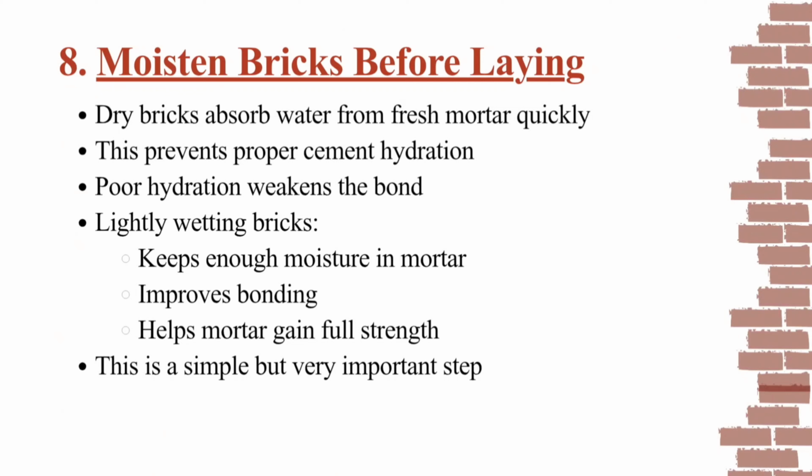So, lightly wetting the bricks ensures that the mortar retains enough moisture to gain full strength. And this simple step significantly improves the bonding between the mortar and the brick. So, this is also important, to moisten the bricks before laying in brick masonry work.